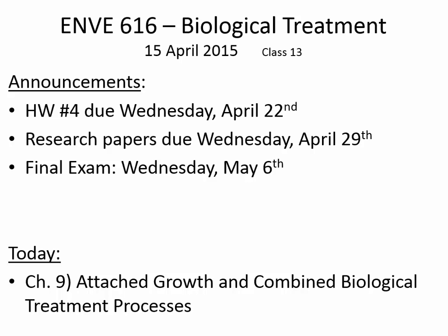in the table it says NB VSS is 40 milligrams per liter, but then in part A I say assume no nitrification and NB VSS equals 0. And so go with what it says in part A. Assume that NB VSS does equal 0. In that part, in part A, what I'm doing there by saying assume it's 0 is I'm simplifying. If you look at the equations, you'll see what the implications of that simplification are.